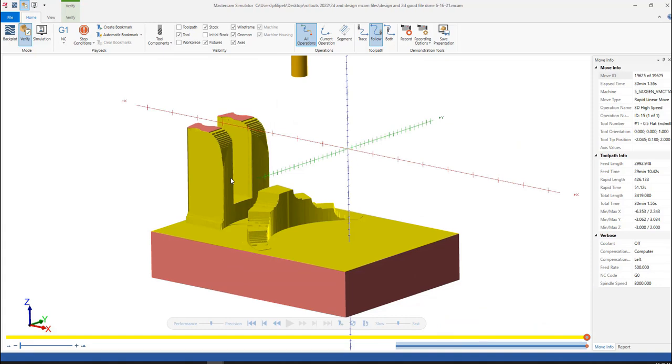Now, if you're a mill customer, you used to do a part like this with multi-surface rough, which would kill your cycle time. Typically what we see with this toolpath is approximately 60 to 80% cycle time reduction on roughing if you can, and a lot longer tool life, 10 times tool life for any material. We do offer training for this, so if you're unfamiliar with it, you may want to consider our dynamic roughing training class that we run bi-monthly. So check that out on our website if you haven't been there.